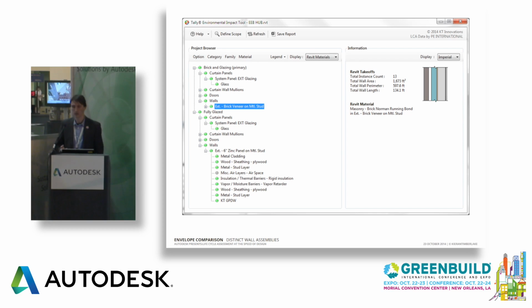So here we're finding not simply that the materials that we're using are different for that single 100 square feet, but in fact we're generating different takeoffs. And those are all leveraging the capacity of the BIM model to generate that information. And then it's simply a matter of assigning the appropriate materials and systems to those using our LCA software.